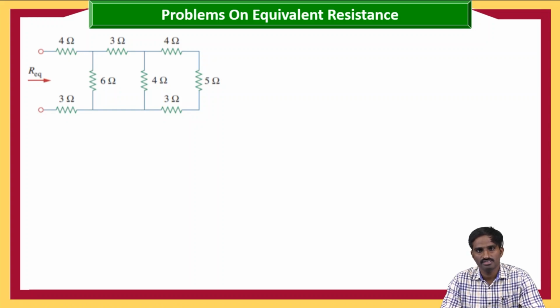For the two resistors to be in parallel, they must have two common points. The condition to make two resistors in series is that they must have only one common point, and that common point should not be shared with any other element, either another resistor, inductor, capacitor, or an active energy source, which means a current source or voltage source.